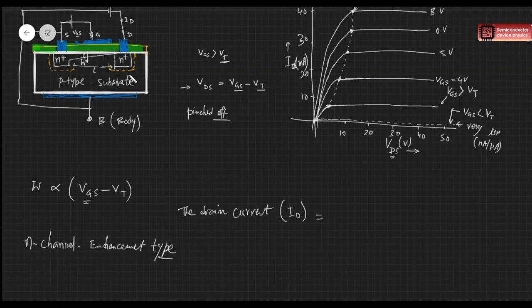This is the N channel MOSFET. So for N channel, the substrate is P. We are creating an N channel, the inversion layer is N type, and source and drain are also N type, right? So this drain current directly relates with W into mu N. I'll come to that. W mu N, then COX, that is the capacitance of this oxide layer. The oxide layer is here, this region is the oxide, right? So it could be silicon oxide or any dielectric material, by 2L.